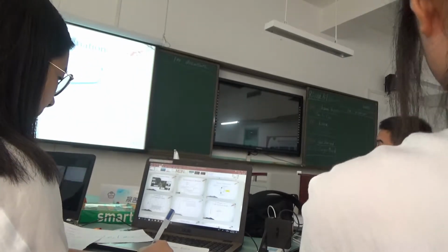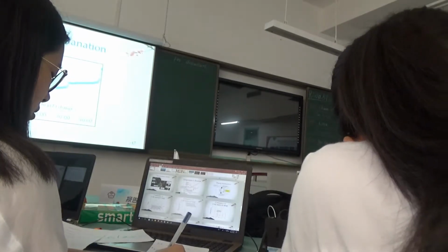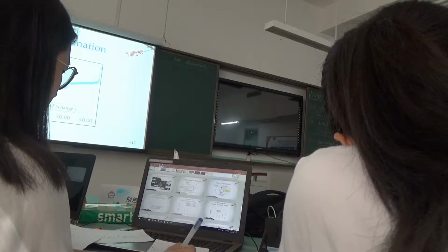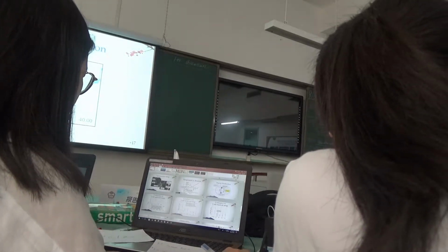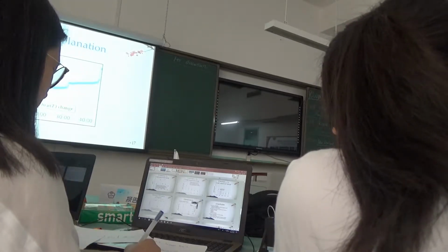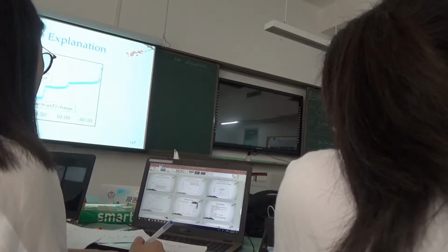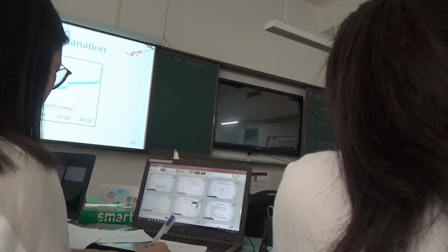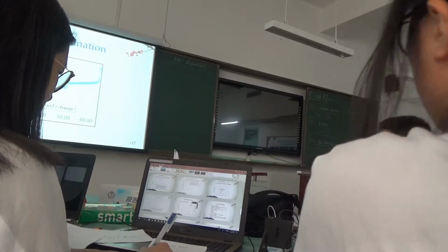So, a qualitative explanation on why the rotation of the Curie engine is not continuous. We can see that firstly, there is no rotation here because the temperature of the heating spot hasn't exceeded the critical point to let the torque caused by the magnet become higher than the torque caused by the resistance. Therefore, there would be no rotation here. Once it exceeds this critical point, it will begin to rotate.